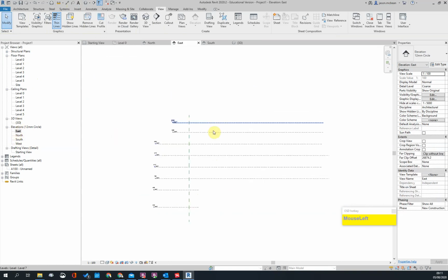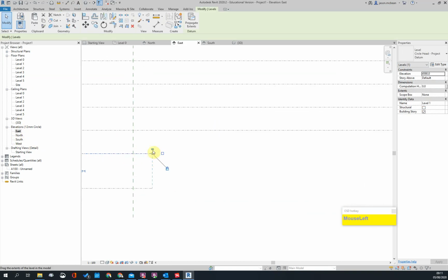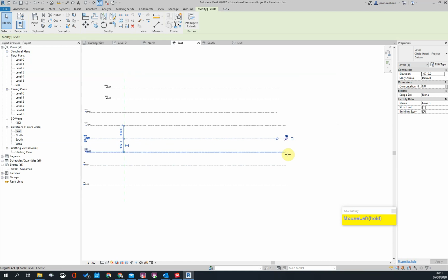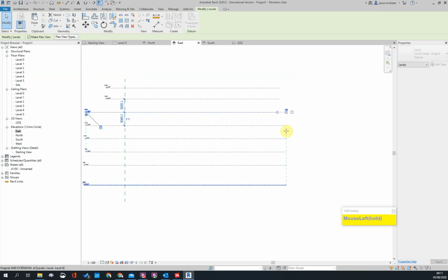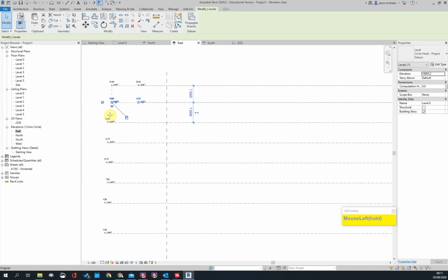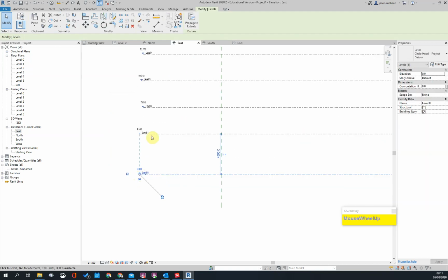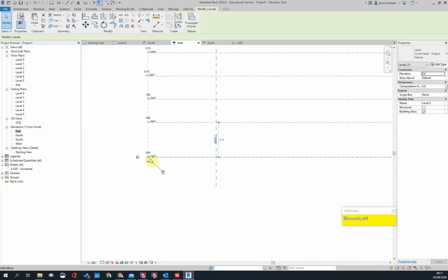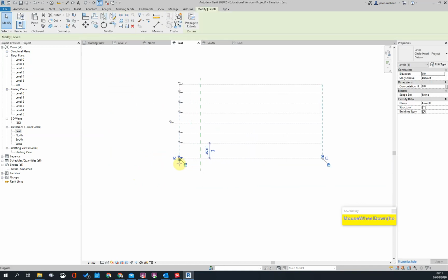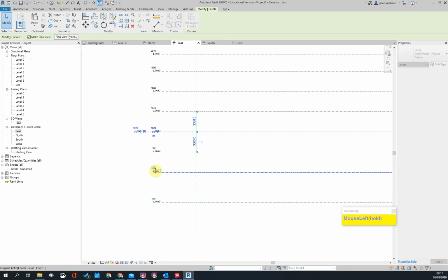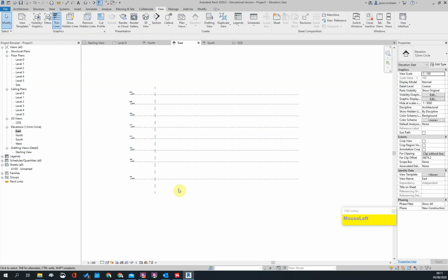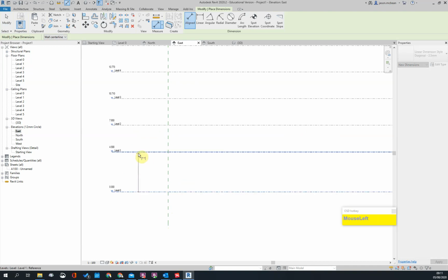There are some other tools that we can use a bit later on to get this to work. So when you click the 2D, 3D, you want to grab the 3D function so that the levels start working together as one. That's very important. I'll explain some circumstances where you don't want that to occur. But it just means if you change one level, so if I grab the level over here and drag it and lock it and line it to that one, you'll see that they'll all start working together. So if I grab this level and move it this way, you'll see that they're working together. You just want to create a relationship with these levels. Now they're all working together. So the ends will be working together. That's great. Next thing I'm going to do is use some dimensions.